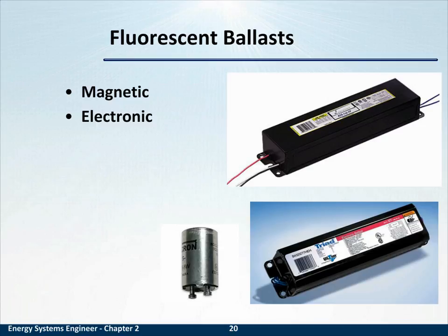In a gas, however, conductivity increases as current increases. Therefore, if left unchecked, the current could cascade to a point where lamp failure would occur. The ballast allows for the conductivity in the gas, such as gas found in a fluorescent tube, to be controlled.